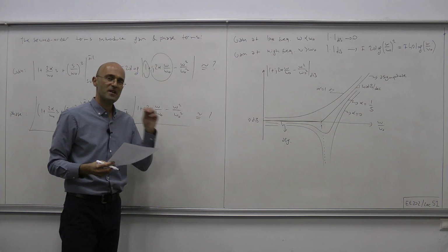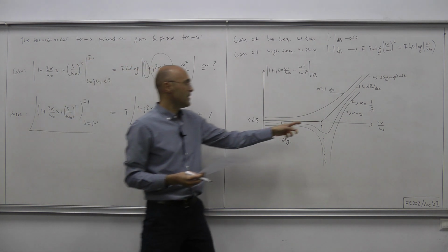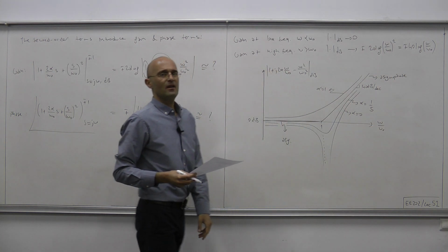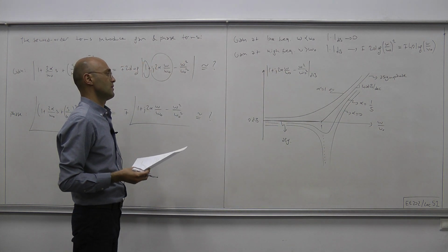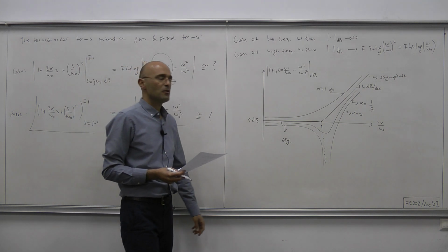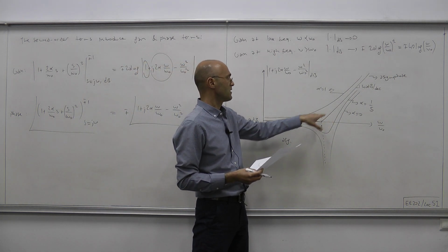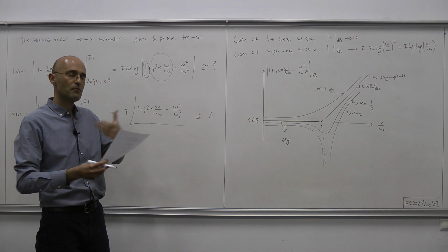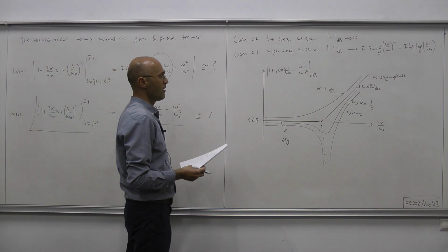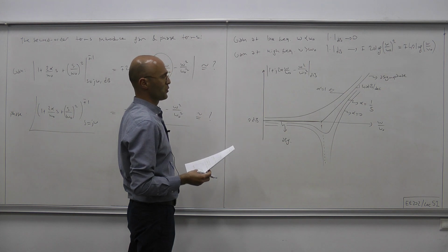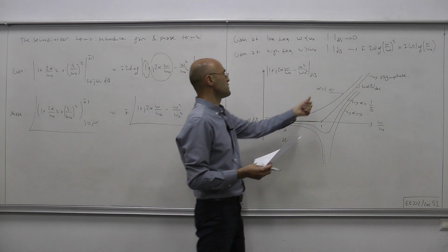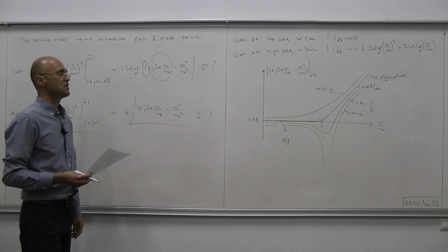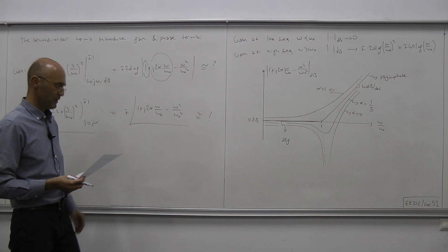So that means if alpha is tiny, then especially around frequencies where omega is around omega 0, the asymptotic approximation is not that good. The actual curve is significantly far from the asymptotes. But if alpha is reasonably close to 1, then the asymptotic approximation is a good approximation for many applications.